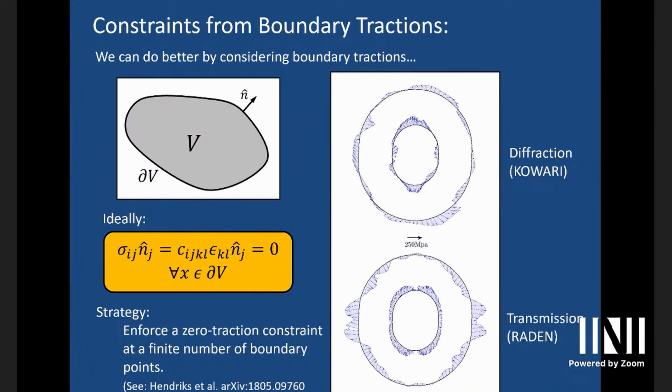Essentially, if you've got a boundary, and you put that gauge volume off the boundary, then you're only getting a measurement from this bit of material. In reality, you're measuring a very precise angle at which the diffracted beam came off, and the shift from the center of that volume from here to here is enough to actually see a change in the measurement. And so you can't have a gauge volume that overlaps the boundary. It'll just give you an error.